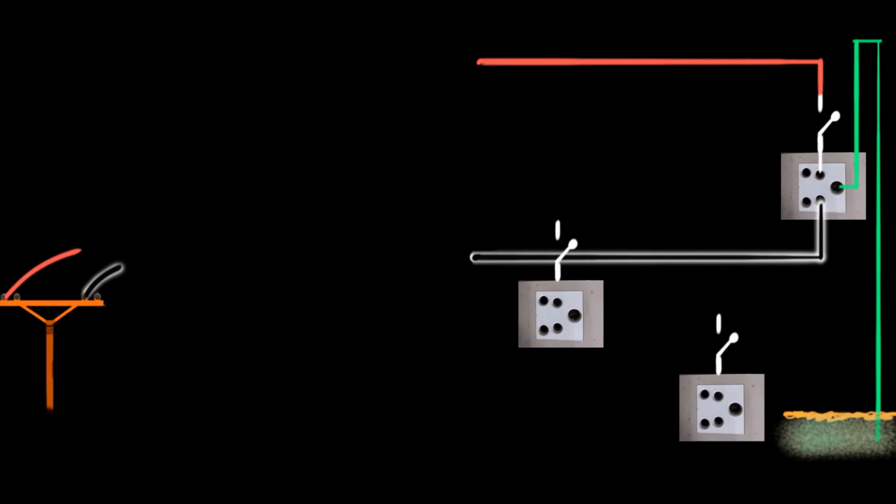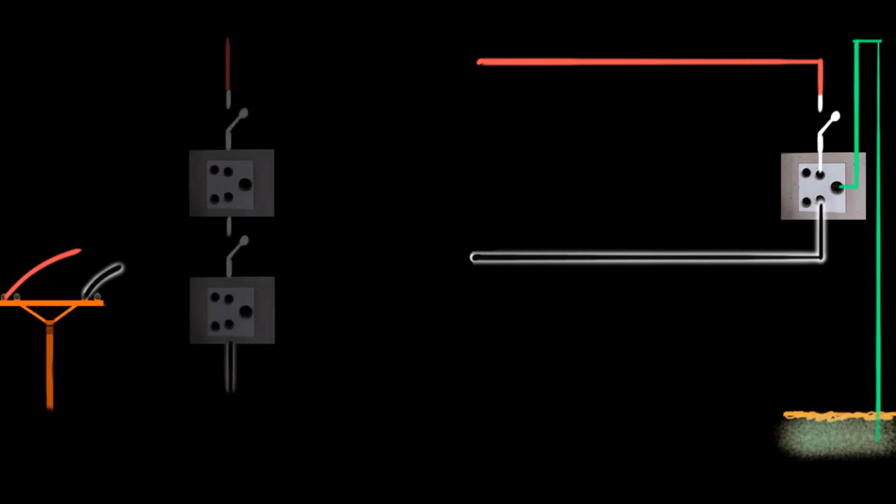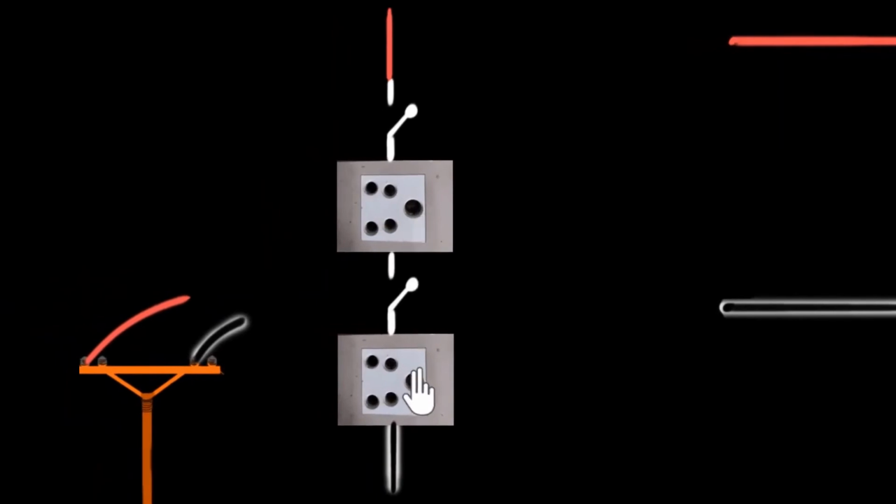All right, if you've given it some thought, let's see. Let's start by exploring the series connection. The series is when you connect them end to end, right? Now, one immediate problem you can see over here when 2 plugs are, let's say, connected in series is that if you were to close one of this switch, let's say I put my mobile to charge over here and I close one of that switch, no current will flow over here. Why? Because this switch is open.